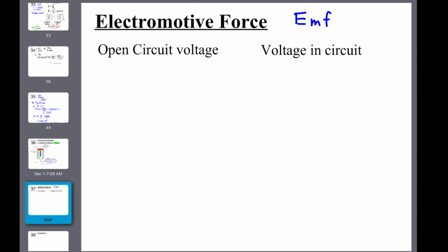Now, I want you to do a little experiment. I have left bulbs, batteries, battery holders, light bulb holders, and the alligator clip wires up on the front board, and the digital multimeters over there on the counter. Turn the digital multimeters, the gray ones, to a setting of DCV, DC volts, 10 volts.